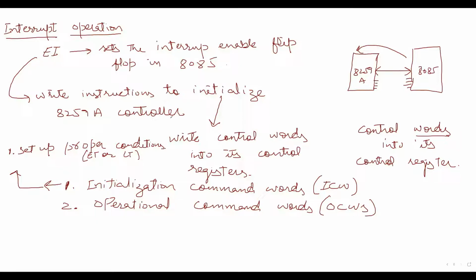Likewise, whether we have a single 8259A device or multiple 8259A devices. Those proper conditions are set up using initialization command words.